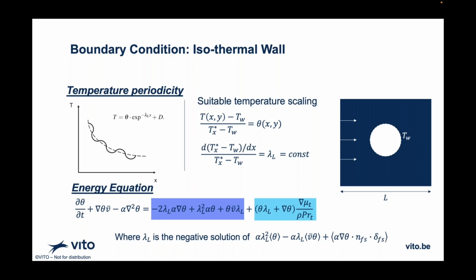To go further, isothermal boundary conditions in conjunction with the flow equations I showed you previously can be very interesting if we are designing an evaporator or a condenser, where we have constant temperature properties. For that, we need a new set of source terms that can represent a similar kind of flow behavior, but in a streamwise periodic flow.